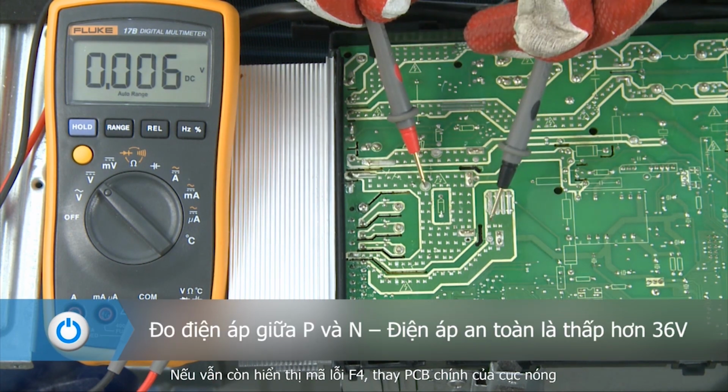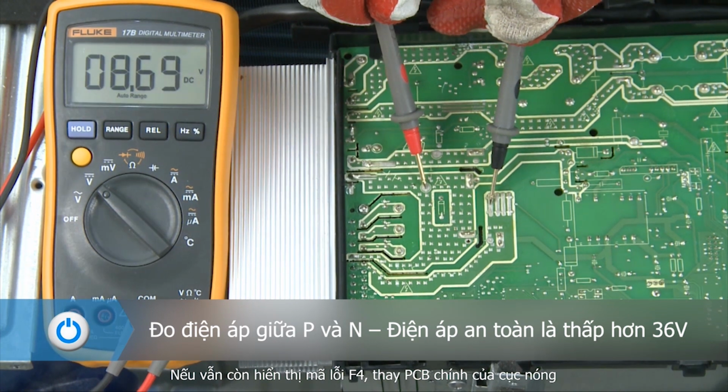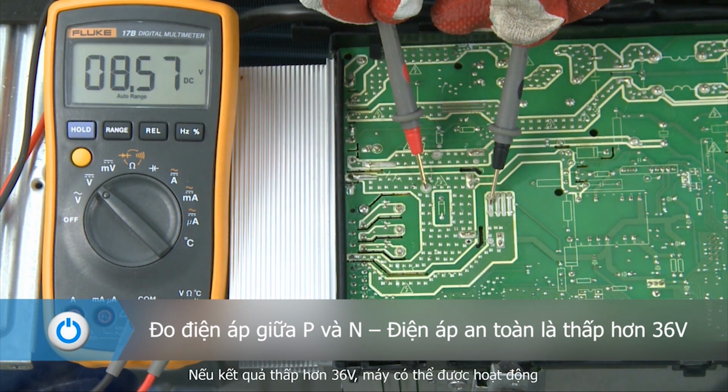Measure the voltage between P and N via multimeter. If the value is lower than 36 volts, the maintenance operation can start.